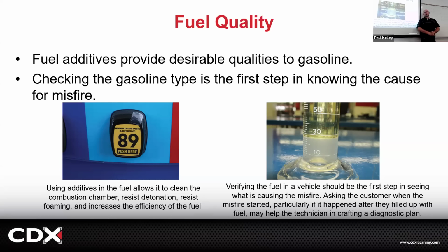How long was this sitting around? Because if you have ethanol in there and it collects water, if that fuel is not sealed, it will continue to pull moisture into it right from the air and just collect and collect and collect. I don't think that someone put water in it. I think that the ethanol collected the water just from not being perfectly sealed, right?